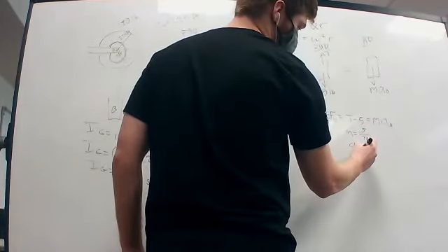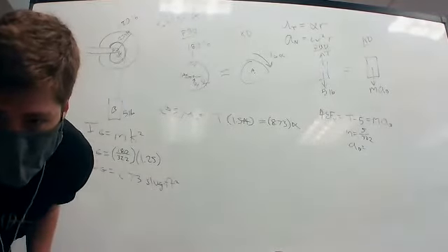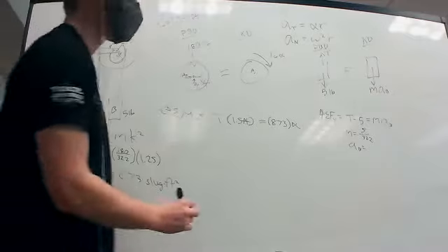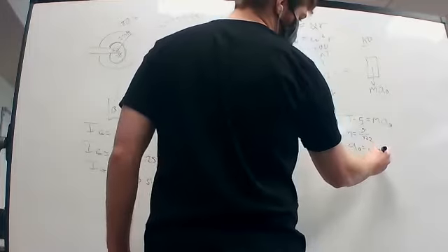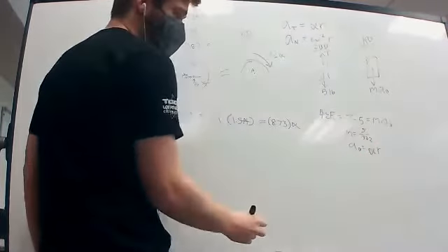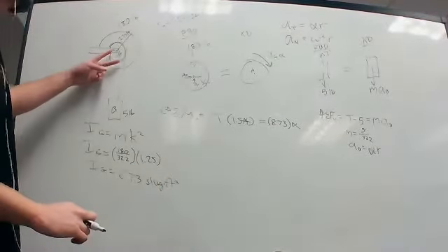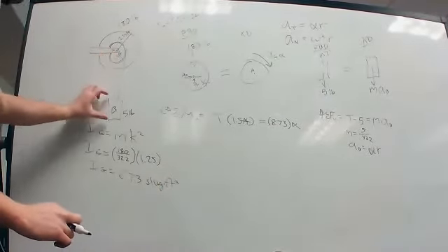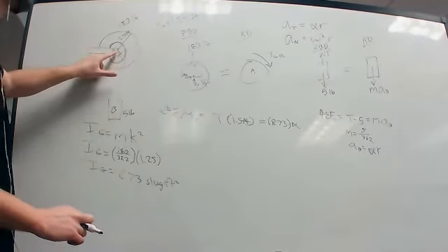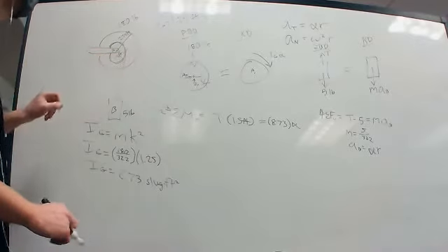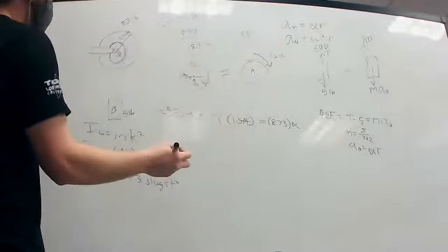And we can say AB is going to be equal to alpha R, and we know that from here, where our R value is going to be 1.5, because basically what we're doing is we can say the acceleration here is the same as the acceleration here, which can be treated as a rigid stick from A to this point. And so that's how we know we can use AT. I'll draw it real quick.